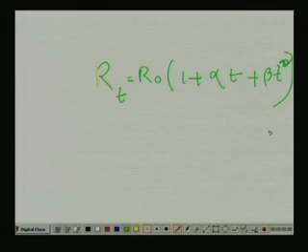So, you can see that in this type of situation I can approximate like this, because higher terms like gamma and all these things will be quite small and can be neglected. The amount of nonlinearity introduced by higher order terms will be very little. If I take it up to beta t squares, it is more than whatever accuracy we need, as we have seen, 0.76% of the full scale. So, it is quite small. Up to beta, that means up to second order, t square, is enough, right.